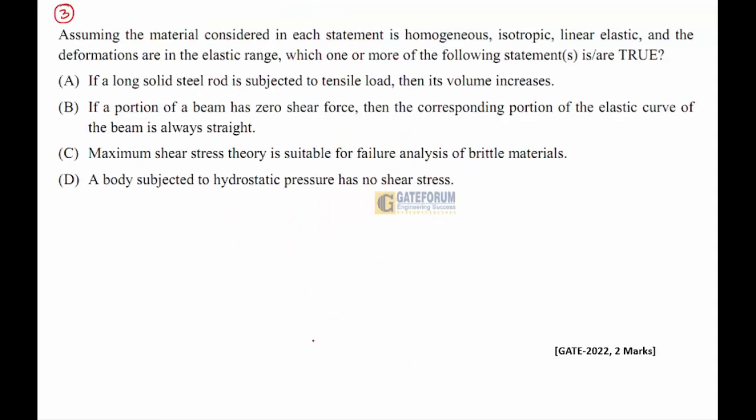Assuming the material considered in each statement is homogeneous, isotropic, linear, elastic, and the deformations are in the elastic range, which one or more of the following is or are true? A. If a long solid steel rod is subjected to tensile load, the volume increases. B. If a beam has zero shear force, then the corresponding portion of the elastic curve of the beam is always straight. C. Maximum shear stress theory is suitable for failure analysis of brittle material. D. Body subjected to hydrostatic pressure has no shear.